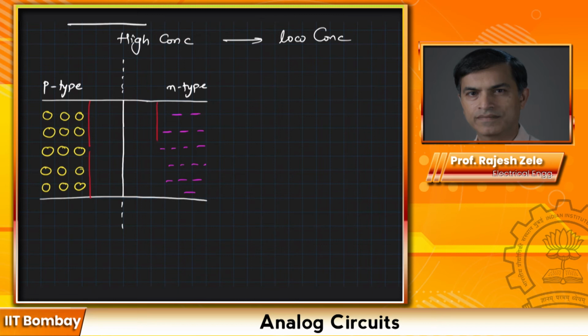And this particular area around the junction will not have any carriers. Some of the holes at the junction interface have left to the n-type, and probably got recombined with electrons. And similarly, when electrons came back to the p-type, they sat into some of the hole locations.